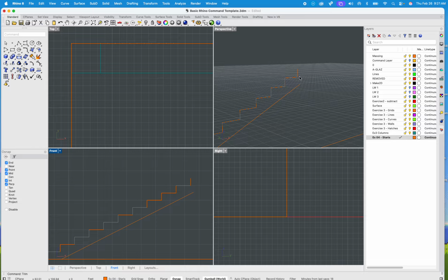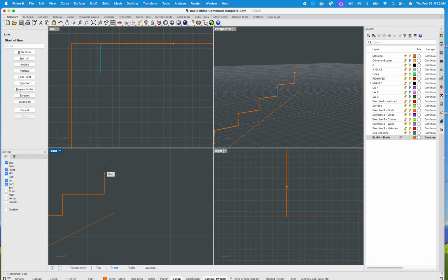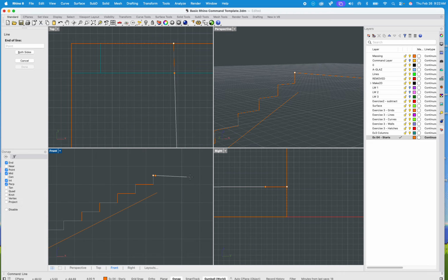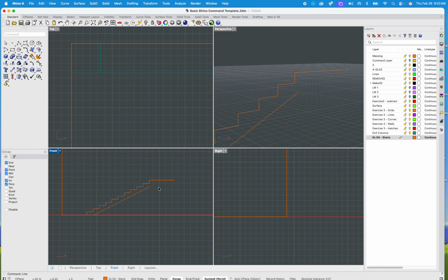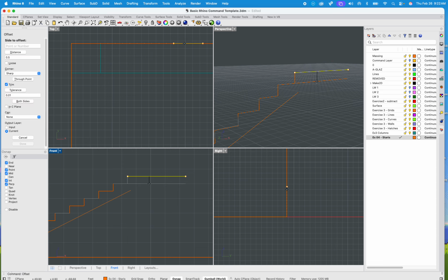All right, let's continue that drawing because that's not going to do so well. Let's complete it, right? So in my case, there's a couple ways I can complete this. I can basically add to that. I can go all the way up. Let's do that. And in my case, since I'm going to go with 4-foot stairs, I'm going to also do a 4-foot landing. Not 4 inches, my bad. 4 feet, shift, sweet. And yeah, I might also want that 6 inches as well. So offset.